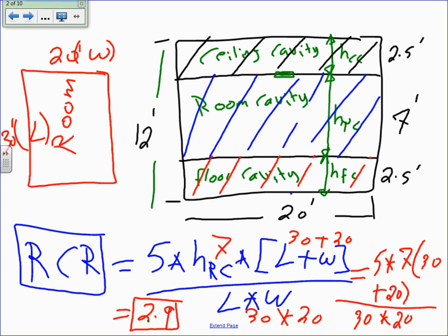when I test you, again, I hate to spend time on it even because there's a lot of software now, but this will help you understand how they calculate the lighting indoor. The first step of calculating lighting indoor is to find the room cavity ratio. How do you find the room cavity ratio? In order to find the room cavity ratio, you need a room. So you need the length and the width of a room. Now, if your room is not rectangle, you make it as rectangle as you can. So you need the width and the length of the room. Cool, that's easy, width and length.